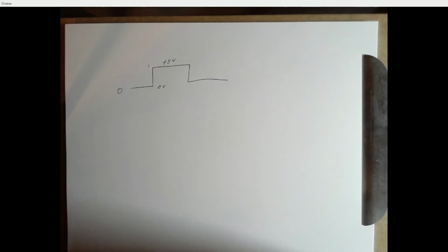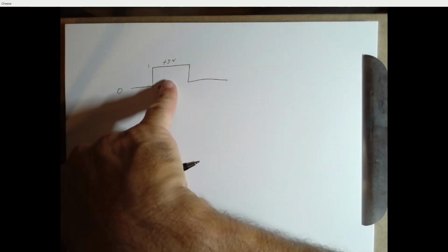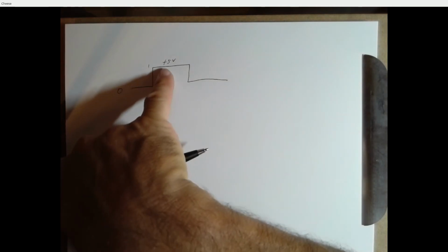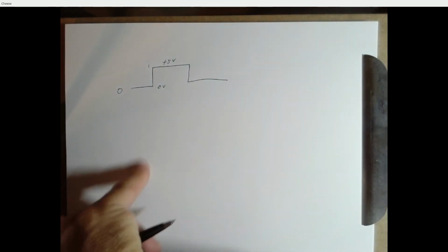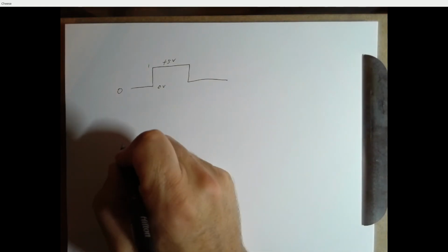What if you want the motor to spin at half speed? One option would be to somehow output 2.5 volts, and the motor would spin roughly at half the speed. But on a digital device like the PIC processor, we can't output 2.5 volts. We can output 0 or we can output 5. But we can do something almost as good. We can do the following.